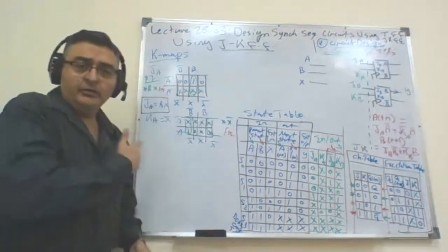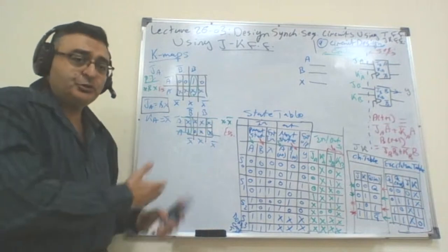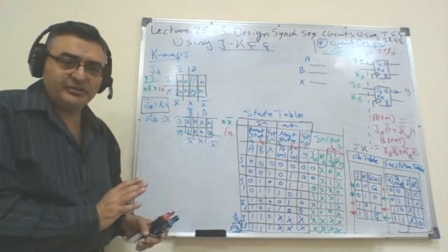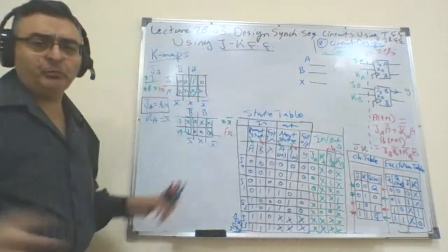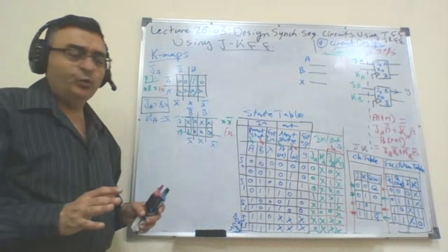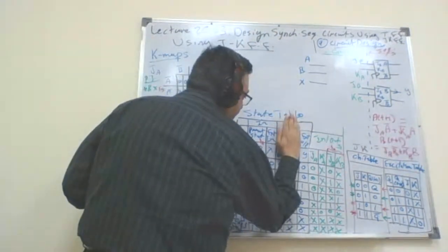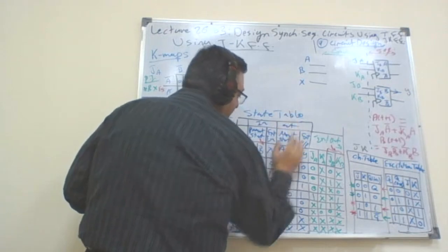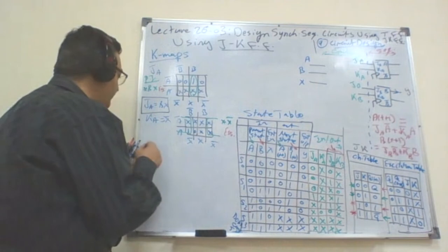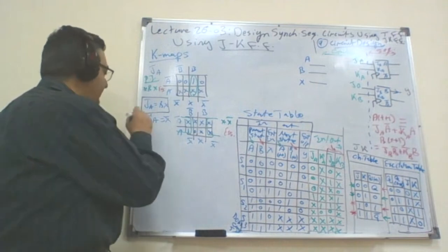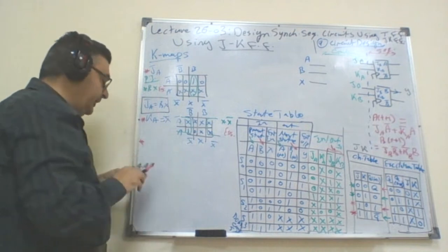By the way, this is chapter 3, so I don't have to do that. I'm just doing that for the sake of completeness. After you derive those, it's a problem from chapter 3, K-maps. You have the table, you forget the states and next states, and you have a truth table. You solve this truth table for 4 variables: JA, KA, JB, and KB.